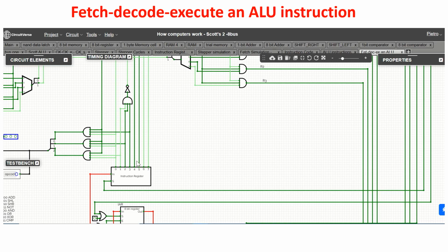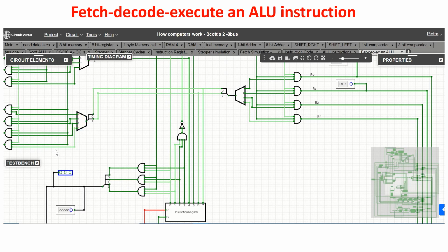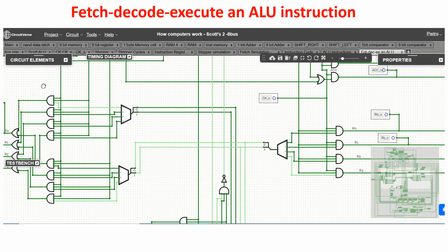We see here the instruction is inside our instruction register because you see in light green the 1 and in dark green the 0, and you see this is 11000011, which is the AND operation between register 0 and register 3. So you see as register B you select the third line, so register 3, here 2, and the first line because it's register 0, so we select register 0.